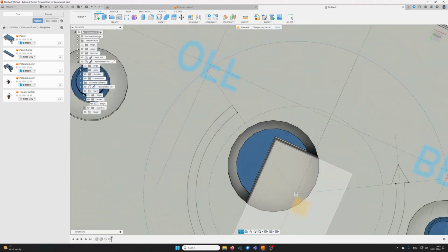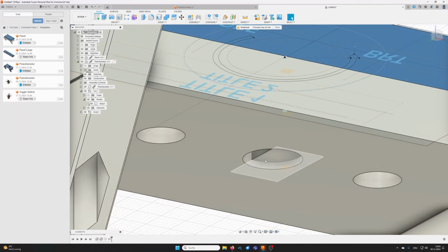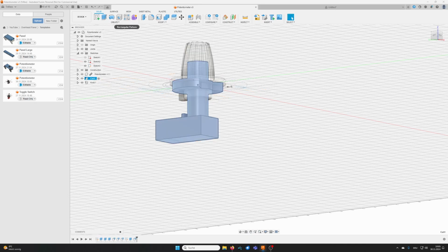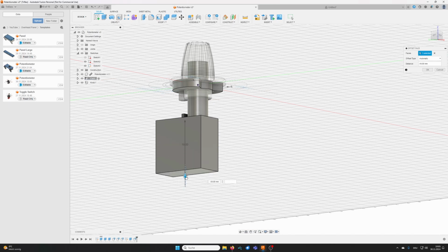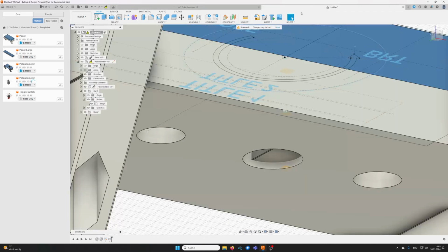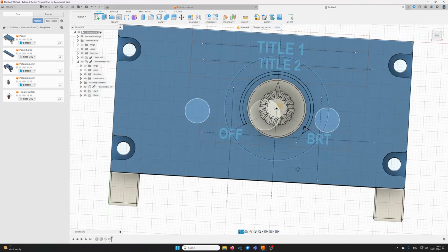Here you can see the cut body has to be a little bit more in the Z- direction. Go back to cut and just drag this face with a press pull 20 millimeters. Save it. Update, and here is the cut body. Perfect.